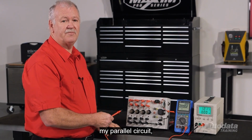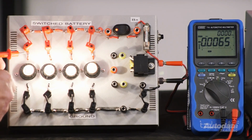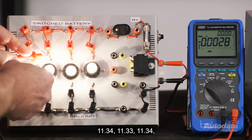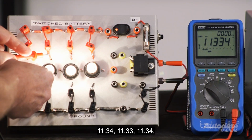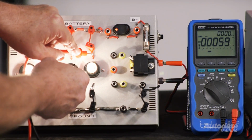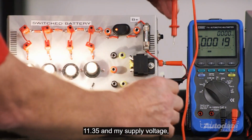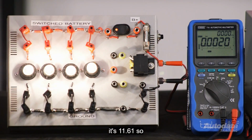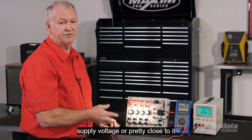I'll do the voltage drops on my parallel circuit. I'll turn it on and I'll go across each globe. 11.34, 11.33, 11.34, 11.35. And my supply voltage is 11.61. So you can see that each of the loads has the same voltage drop as the supply voltage, or pretty close to it anyway.